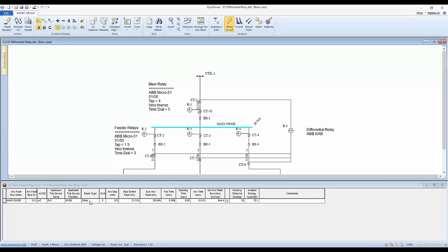While that's what we want to happen, as long as we knew this was the faulting circuit, that would be acceptable operation, but it doesn't protect this whole zone that we're concerned with. As I say, this can include a transformer or even multiple transformers based upon how we've designed our system.